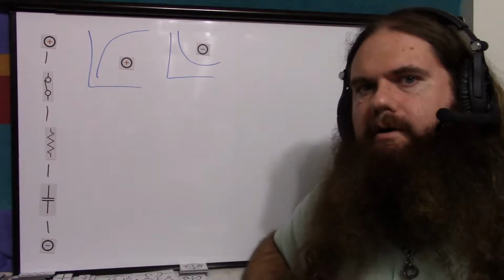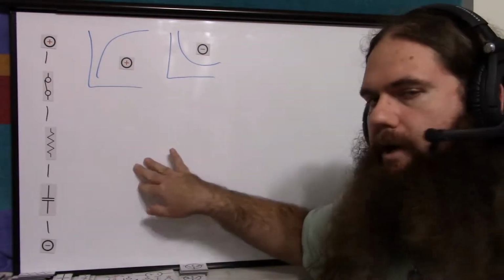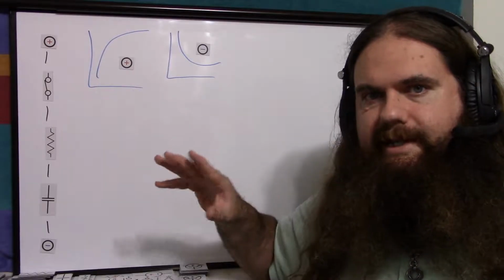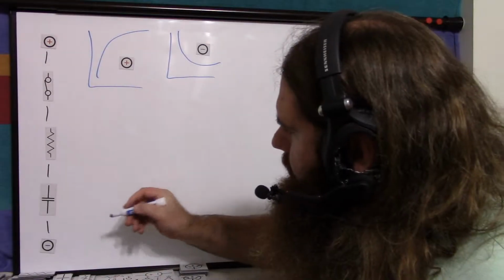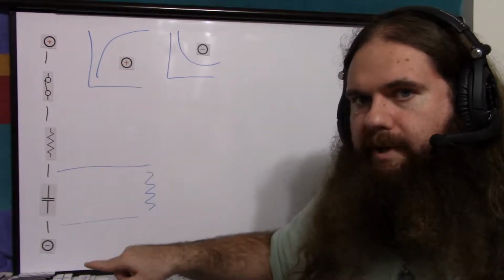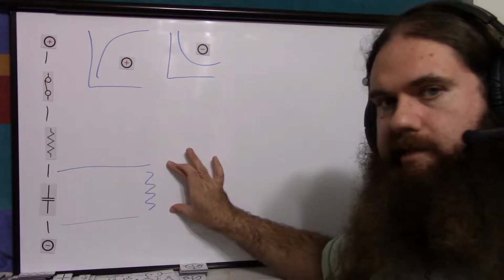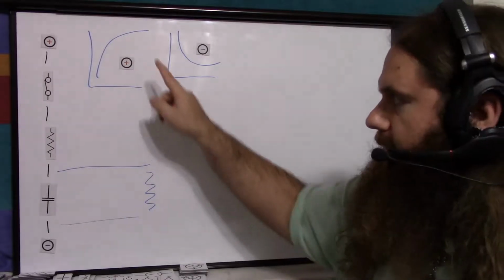This arrangement is called a low-pass filter, if you recall from me showing you the Fourier stuff. And we'll do this in another video on the oscilloscope with real components so you can see it in action. But basically this is a low-pass filter. If you take the voltage here, so this is your low-pass filter, the positive and negative is your signal in, and this is your signal out. Like I said, I'll demonstrate it later, but this is a low-pass filter. That's how you wire it up.